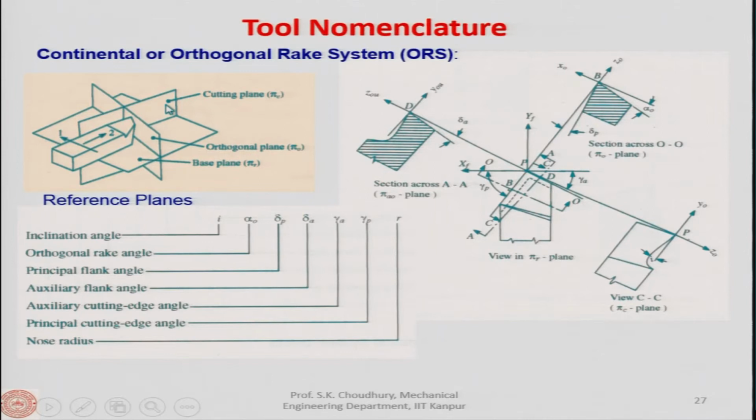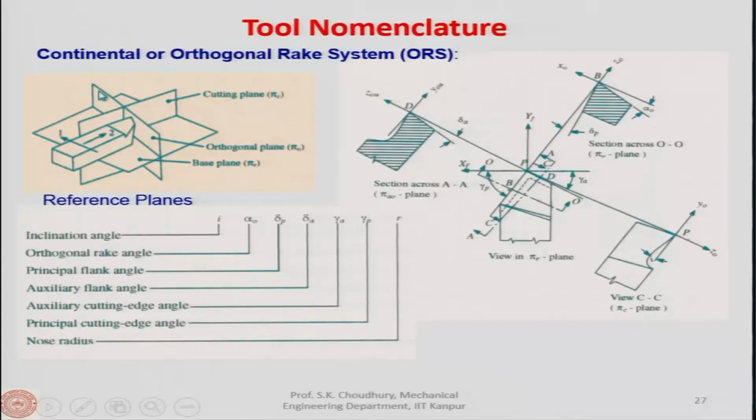The cutting plane is the plane which will contain the cutting edge, it will not cut through it. The cutting edge is lying on the cutting plane, that is the cutting plane containing the cutting edge. Now, perpendicular to that is an orthogonal plane. The orthogonal plane is actually perpendicular to this.